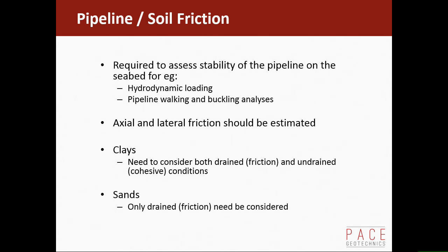However, over time, the clay does actually act as a drained material, so you do have to consider both scenarios when you're designing your pipeline. The undrained behaviour will be the immediate behaviour, but over time it might migrate towards a drained behaviour.